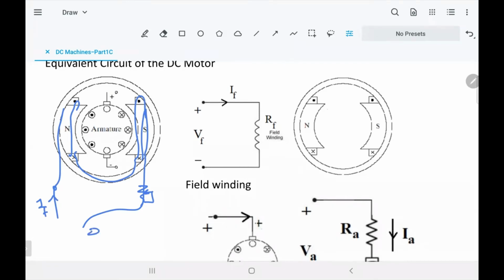So you can say that the flux is proportional to IF, of course, if you don't have a permanent magnet DC motor, if we have something like that, excited externally. So you will see even in the lab, there is a winding and there's a rheostat, a variable resistor, and then you will bridge it. So you connect them so you can control the field current.